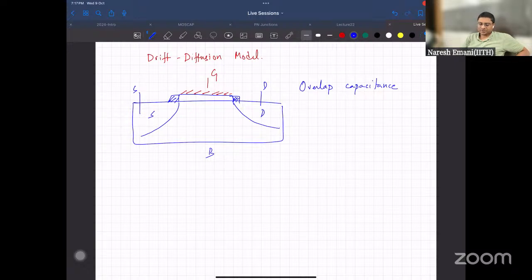Well, the way we measure capacitance is, it's not a linear capacitance, it's a non-linear capacitance. We agree to that? It's not a fixed capacitance. It will change as a function of voltage. So what you do is you have a DC bias, VDC, and on top of this, there is a small AC. You essentially do dQ by dV. This is what you're trying to do.